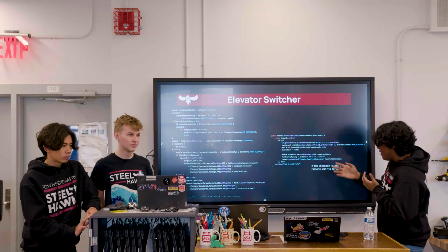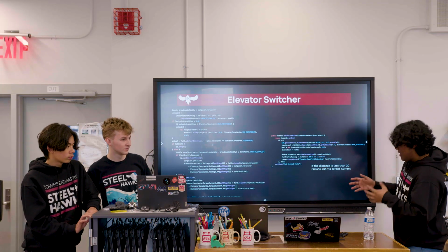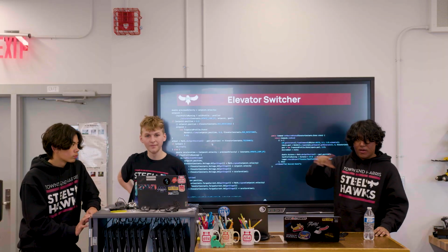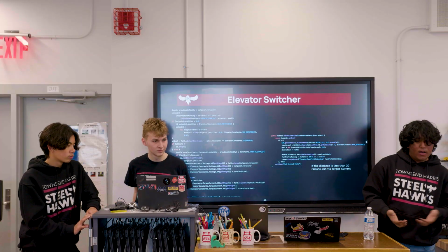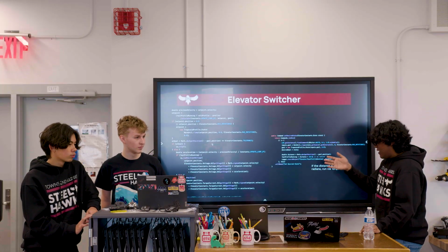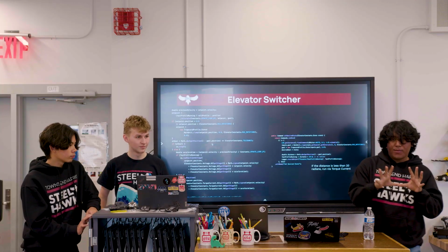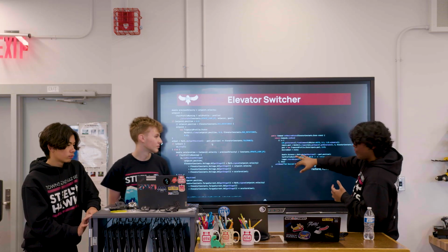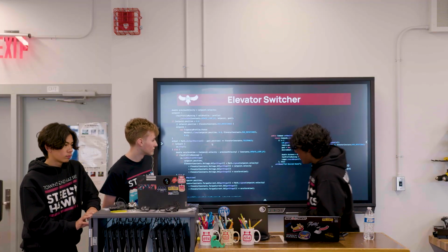And if our distance is greater than 20 radians, which means, L4 for our robot is at, I think, 23 radians, so your motor spins 23 radians. Like I said before, we didn't convert to linear set points. If your distance is greater than 20, you would probably benefit from the higher top speed, because you have more time to travel that distance. So if this is true, you're going to run the fast profile. Does that make sense so far? Yeah, okay. Now I'm going to go onto this side.